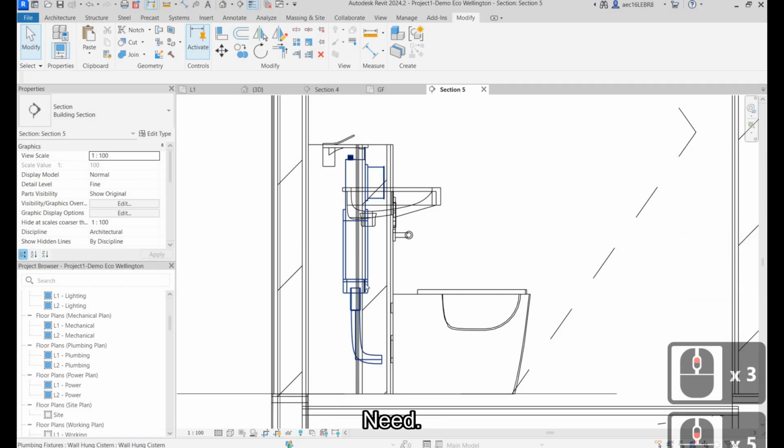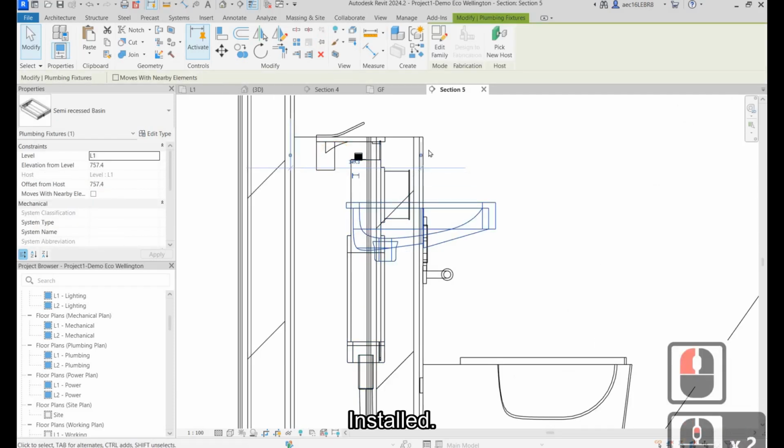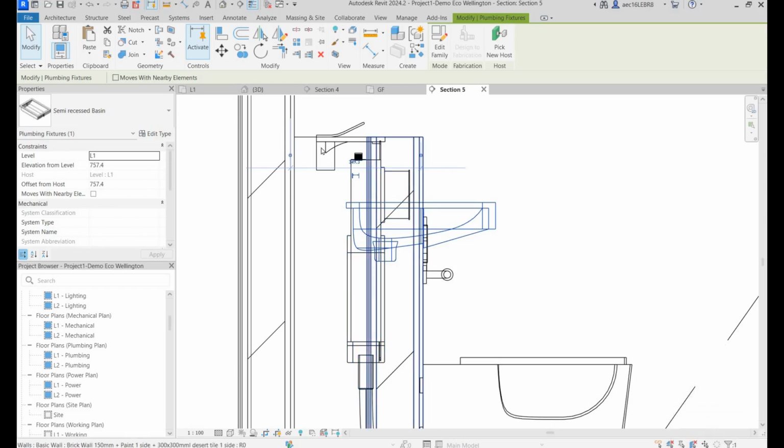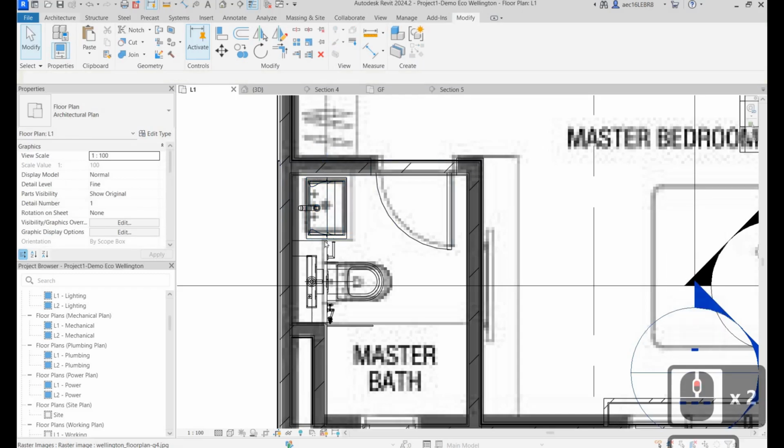So sometimes you need to consider that type of the cistern, because it will affect the height of the basin over here. So normally basin won't be installed higher than 1 meter. So that will be the limitation of your cistern that you need to coordinate. Because if you want the one piece of countertop, let's model the countertop first. Normally it will be one piece without a different height, yeah.